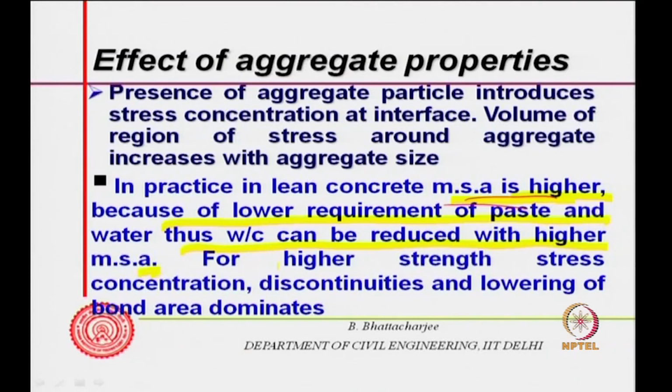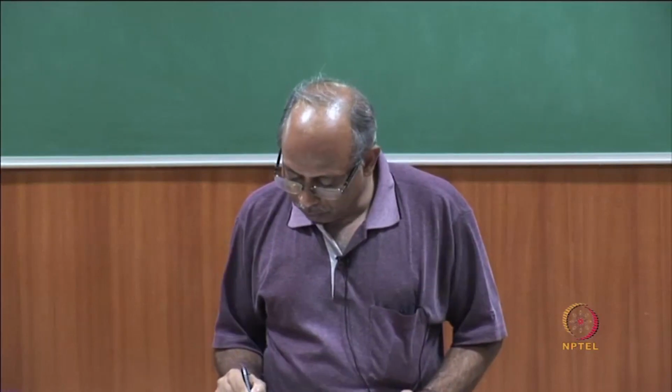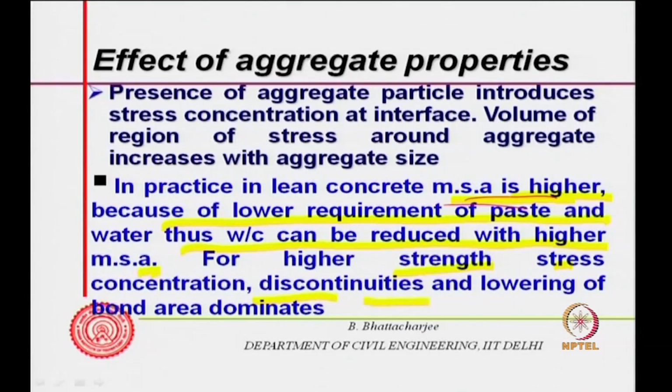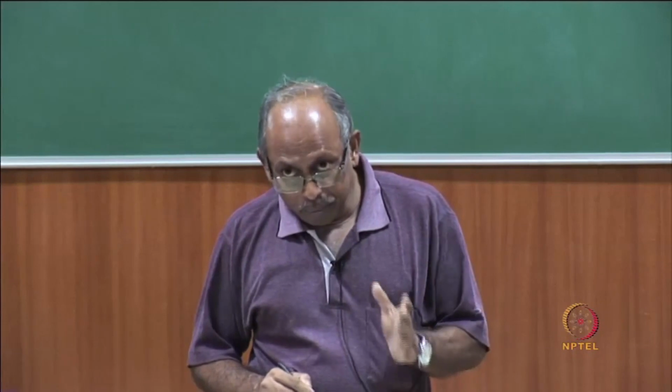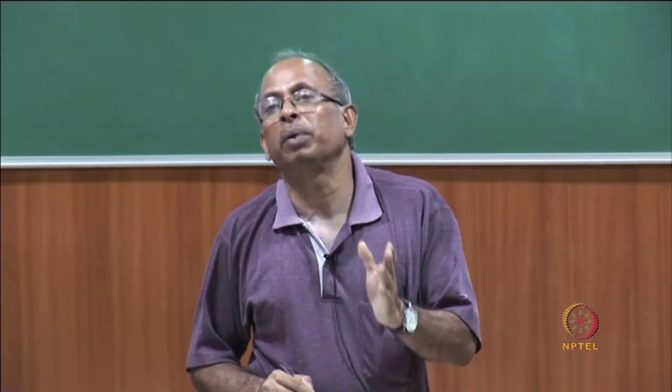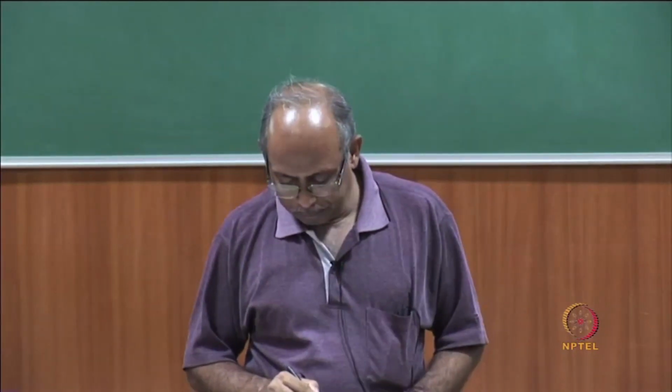You can have low water cement ratio, but higher MSA, then paste should be less. For higher strength, stress concentration, discontinuities and lowering of bond area dominate, and therefore your MSA is limited to a certain value, something like 20 or 40 for structural, as I mentioned.